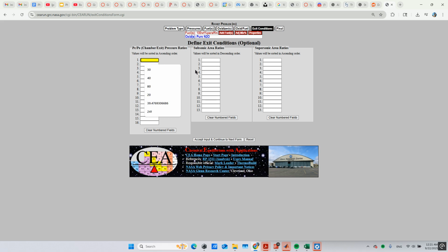So in this case, my ratio would probably be like 29.456, or I don't know, it should be around 29 something, and I got that by dividing 30 bar by the atmospheric pressure in bar. So that's why I have 29.564. And beware, if you do not put anything here, you will not get anything at throat or nozzle exit because it's unable to define a nozzle for you, and therefore you won't be able to get things like expansion ratio that you need for the engine.